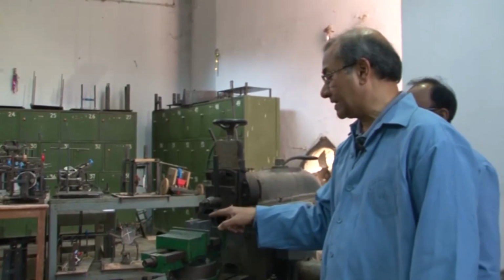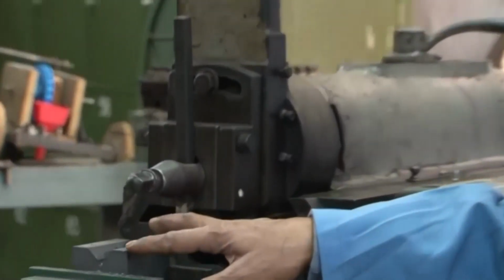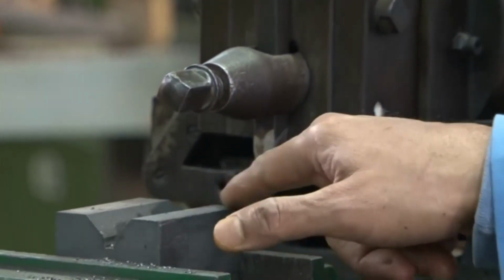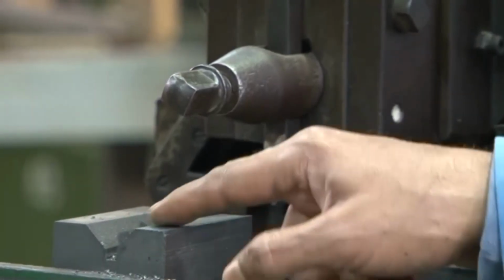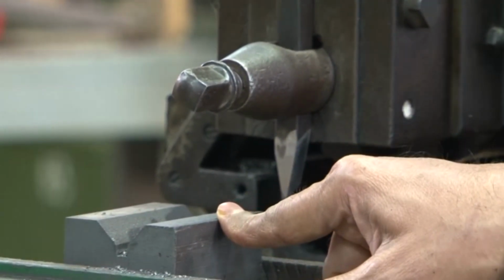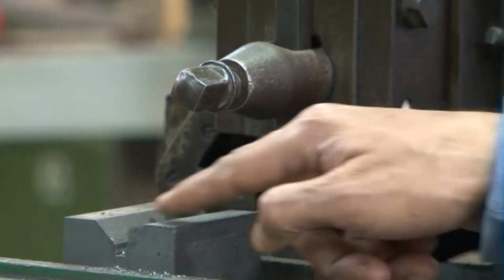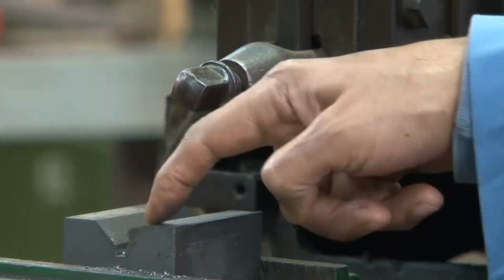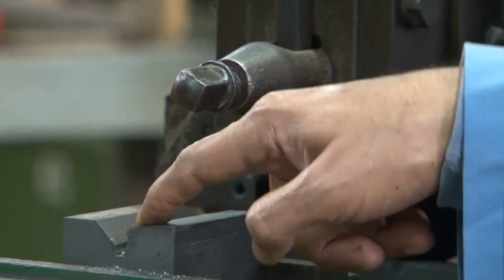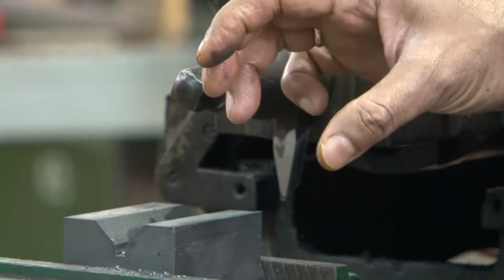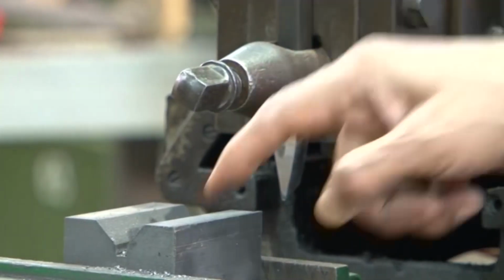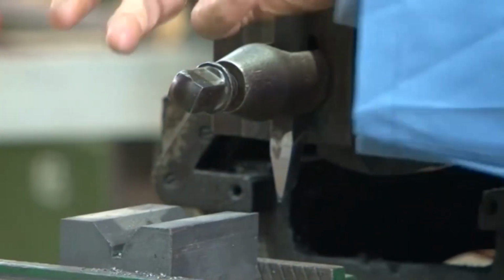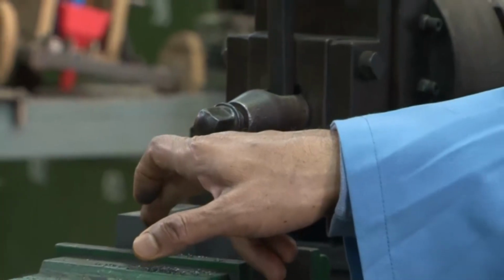So, actually you can see that the flat surface is being made. Now, for the demonstration purpose, this groove was made, this flat surface was also made, but again a final pass has been given just to speed up the process, but otherwise you understand that the same way the entire surface will be produced, and then the tool will be inclined according to the angle which is given for the dovetail, which is 45 degree. So, it will be inclined at an angle of 45 degree to this side when the inclined surface will be produced, and at an angle of 45 degree to that side when this surface will be produced.